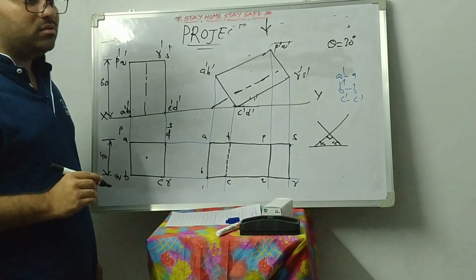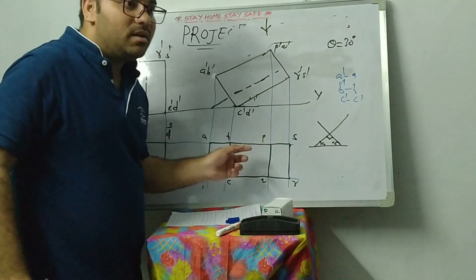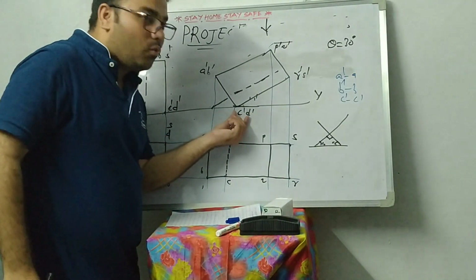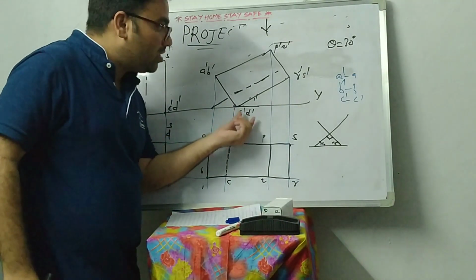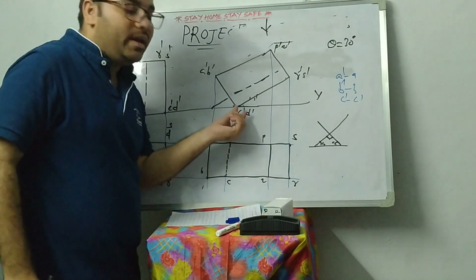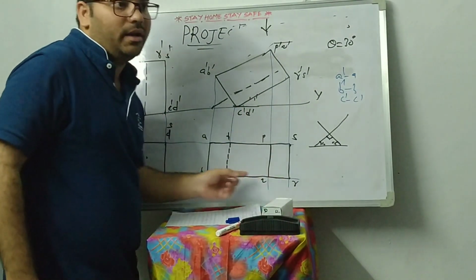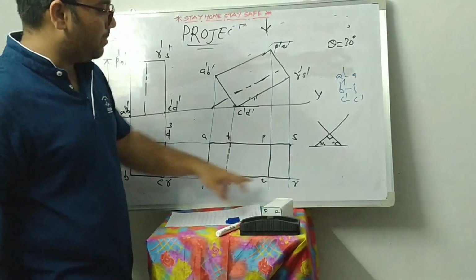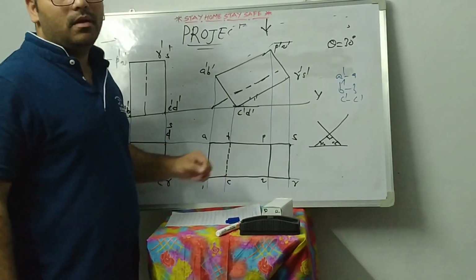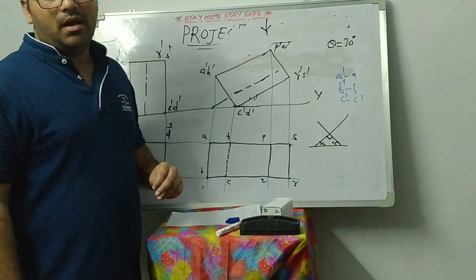If you have any doubts regarding the hidden lines, simply, whatever points are nearer to the reference line, those should be indicated by hidden lines, and the remaining portion should be darkened. Now you can see the square prism. This is a condition. I hope you understand, and thank you.